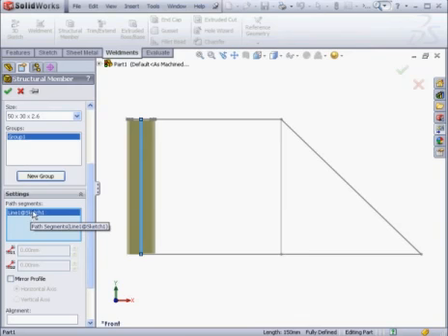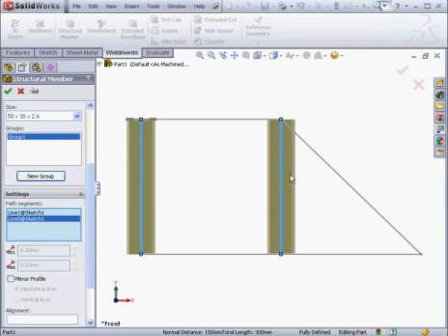We're able to create two types of groups, parallel and contiguous. Let me demonstrate. Here's a second sketch segment parallel to the sketch segment I selected first. Let's select the parallel segment. Now two path segments appear under the Settings control section, and they both belong to Group 1. Because this second segment was parallel to the first segment, my group is now a parallel group. I won't be able to select any other segments that aren't parallel to the first segment, and hence I won't be able to select any other entities in this sketch. While we didn't explicitly define the group as a parallel group, our selection of segments determined that it would be.